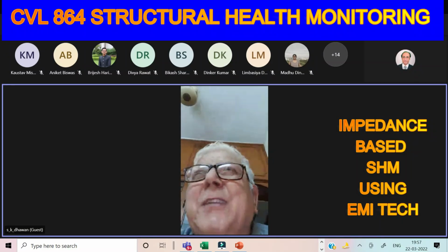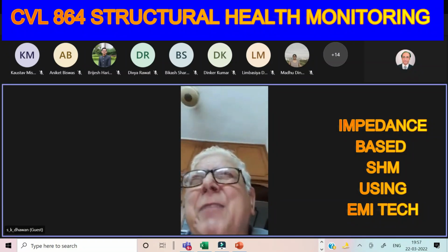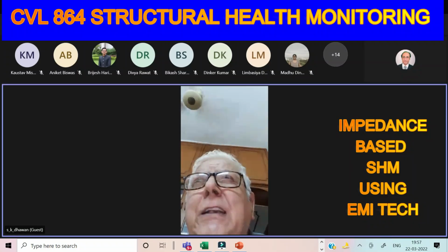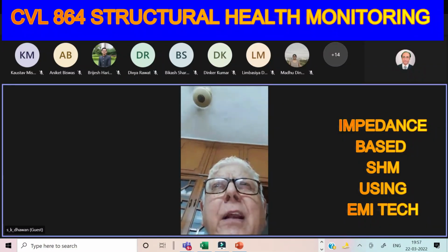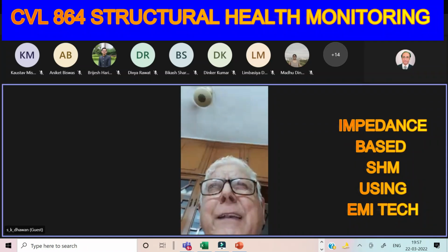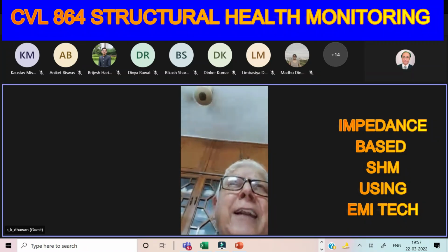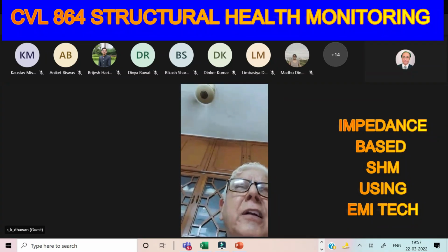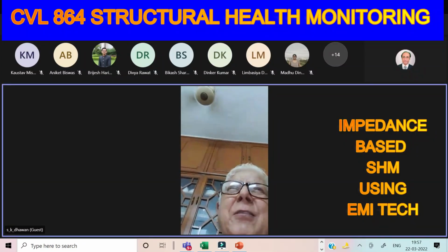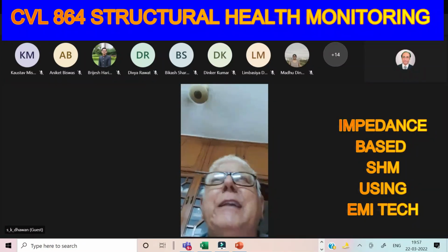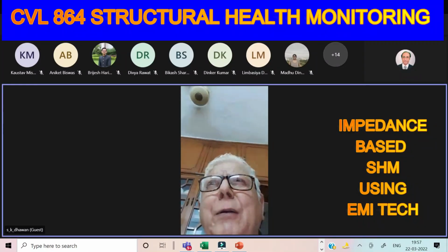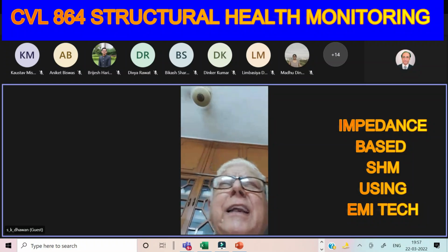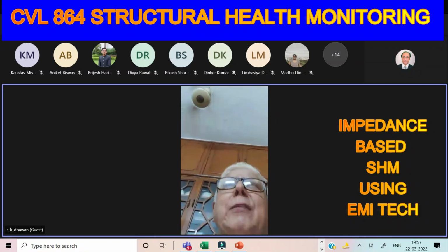I just wanted to share what I actually used, did the experiment, and got the results: with respect to time, with more damage, stiffness gets reduced. Mass also gets reduced. And the capacity of the structure also gets reduced. You are getting more and more damage, and the accelerated chloride damage is a function of time.